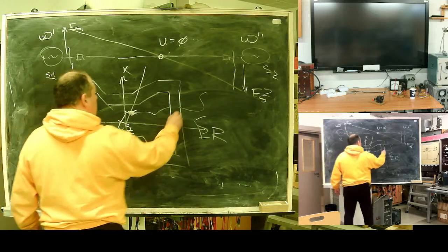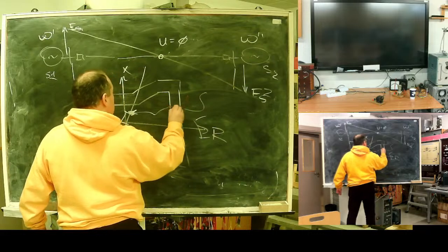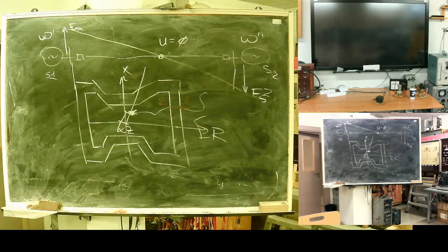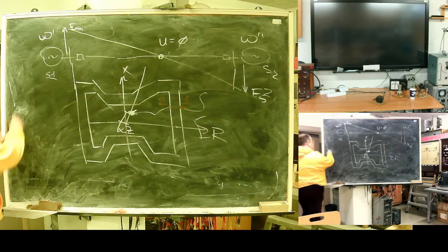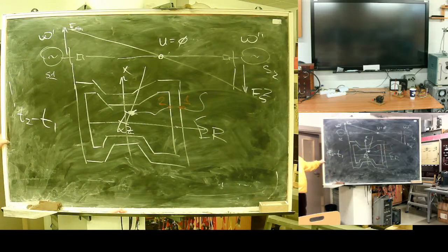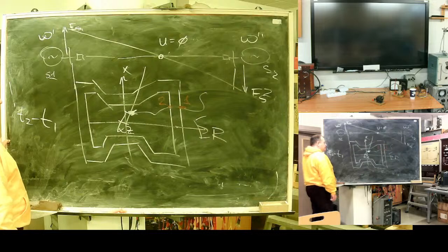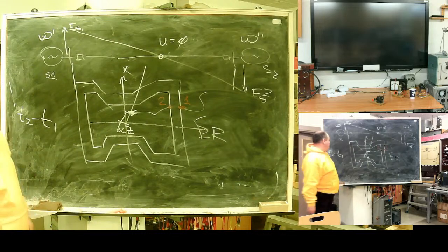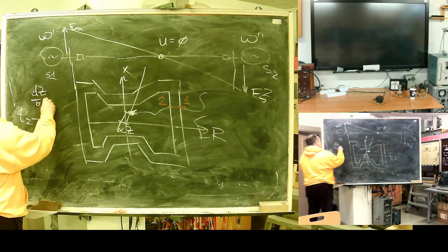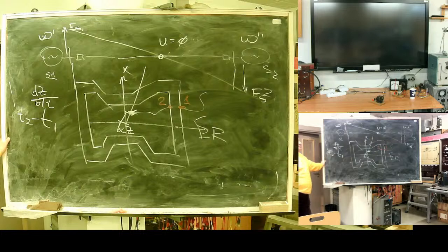There will be two events. One event, two events, when the outer and inner zones trip. Time 2 minus time 1 gives me an estimation of the speed. It's a way to protect ourselves from misoperation during the power swings.